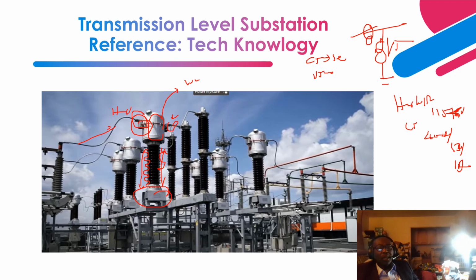Okay, so the primary winding goes through like this, right? It's a single conductor. So this is what you see. This is the primary conductor that goes to the CT, and the CT has a core. And on the secondary are many turns, to achieve the 5 amps or 1 amp. That goes out to this terminal box, then it goes to your protective relay elements.